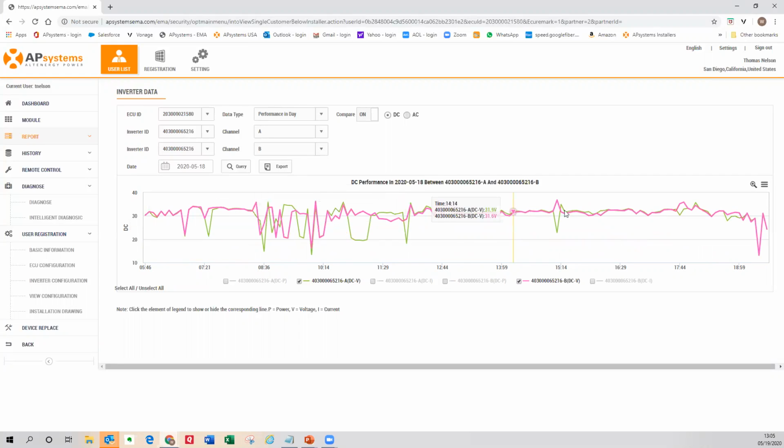So I'm actually able to see DC voltage. Like the example that I made earlier, I was clearly able to see that one was running at 32, 33 volts. The next one was running over 22 volts. Clearly being able to see that difference, the bypass diode that was out and not operating properly. Again, a great way to troubleshoot something remotely from your chair and never leaving your office. And if you do need to leave the office for any reason, if you do need to roll a truck, at least you're now armed with information. This information is readily available and incredibly powerful.